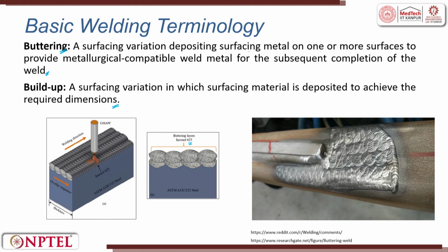Focus here. You can see there is a welding electrode which goes on top of Inconel 625. Here, this is one layer, this is one layer. Between two layers there is something called an overlap, right, and within one layer itself there is again an overlap. This makes sure that you will have a proper weld. This is the overlapping sequence and this is the weld direction. You see the buttering layer is on top of Inconel 625.